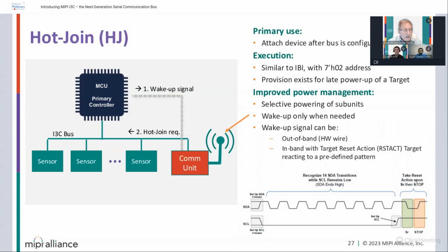You will see in the spec that there are similar patterns used for a number of functions, where by wiggling the data line, it performs some hardware function. In this case, if you wiggle the SDA 14 times, this can generate a reset or wake up signal to the target. So no extra wires are needed. You just use the bus protocol.